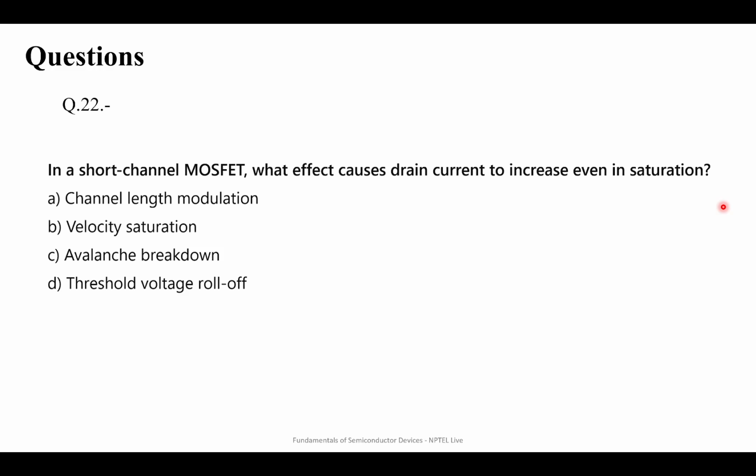Sir, is this channel length modulation? This is answered with channel length modulation. So when you're increasing your drain current, it is affecting the channel near the pinch-off region, where the drain region is connected to the channel. It is affecting the channel length there.